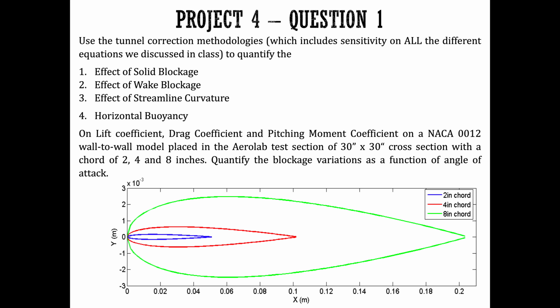Again, we'll talk more about it in class on Thursday, but if you have any questions about this, just let me know. Look at the handout that I gave last time; all the equations are listed in there. I know there are a lot of equations for wake blockage and solid blockage. When you code it, you're not doing this by hand, so you can code it in MATLAB and see how different equations correspond to different variations in blockage, just so that you get an idea of what the equation does.